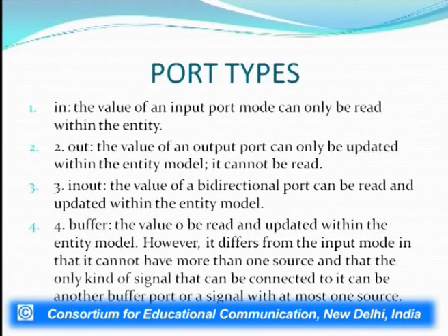Now, as I was mentioning, the port types that we have seen so far are the in and out types. Besides that, there are certain other types of ports that can also be used while defining an entity. In port is there, where the value of the input port can only be read within the entity. Out stands for the fact that the value can be updated within the entity model, but it cannot be read. That means it can only be written into. Third type is an in-out. This type is a bidirectional port. That means you can read from it and write into it.